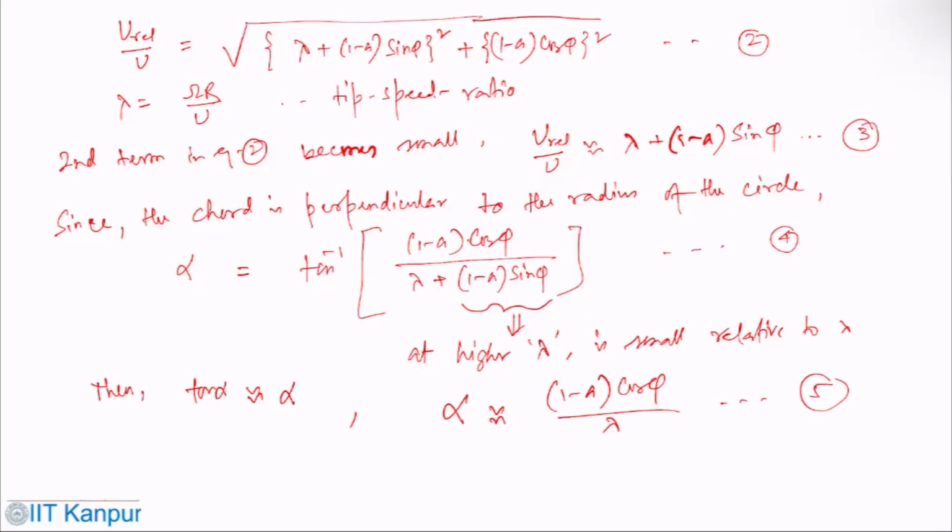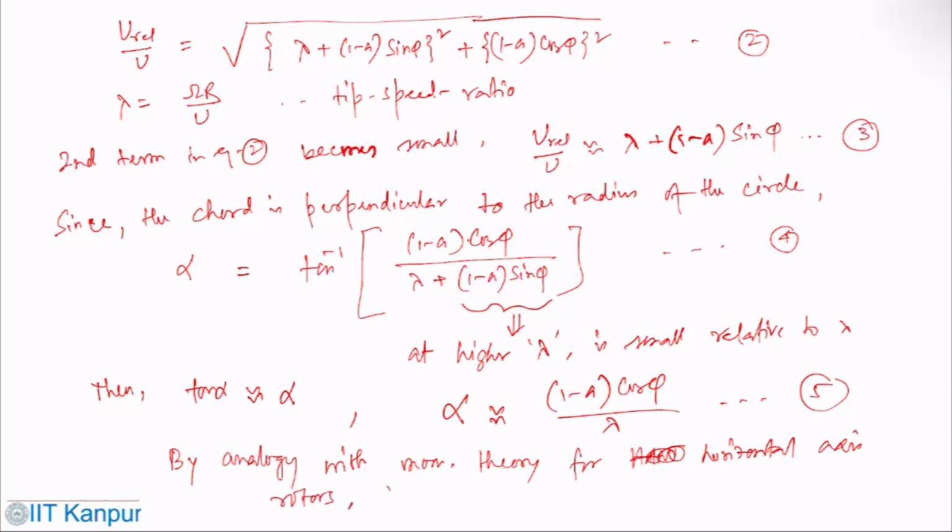Now what we can do, by analogy with momentum theory for horizontal axis wind turbine, horizontal axis rotors, the forces on the blade can be related to the change in momentum in the airstream.